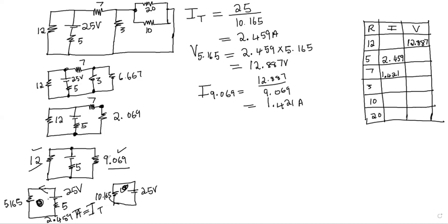Since I'm going back, the type of connection is telling me what I need to calculate. For example, I'm moving from the 10.65 total resistance. I'm going back. What do I need to calculate? It tells me to calculate the total current. Why? It's because my resistors are connected in series. Since I say series, I will have the current through them.